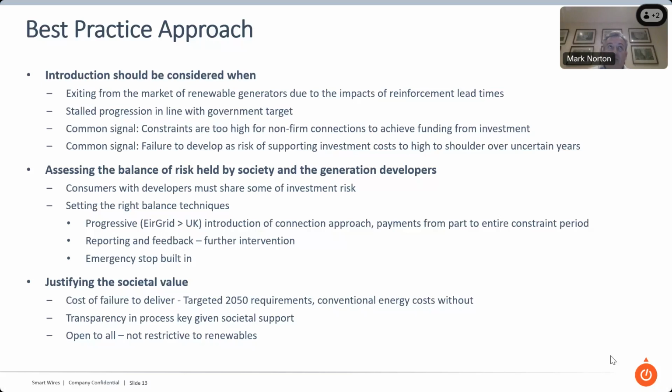And in some cases, bear in mind, modular power flow control could be capacitive as well as inductive. You can even reduce things like losses or move yourself away from resonant points that may be occurring, or harmonic or power quality issues. So, yeah, it's a complicated one to answer, but it solves as many problems as it creates, and it can actually solve some of the problems it creates at the same time. I haven't got long enough to explain that properly, but yeah, I wish I could.